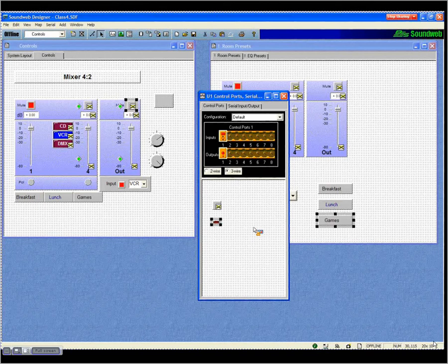It is not designed to directly drive most relays. If you're going to drive a relay with the control output, you're going to have to use a little teeny tiny reed relay, a little small relay, to trigger the larger one. Or, fun trick you can use, you can actually treat the control outputs, if you like, as though they were contact closures. You can wire up an external power supply, run it through the control outputs, trigger a heavier relay.